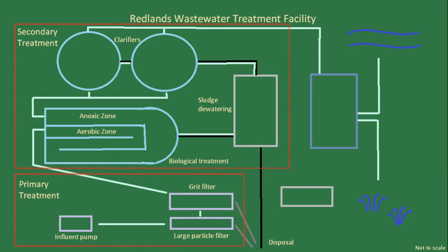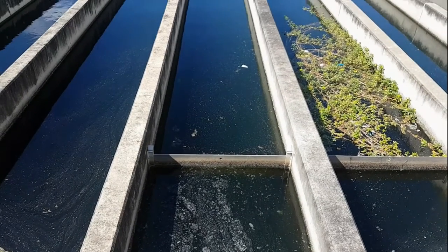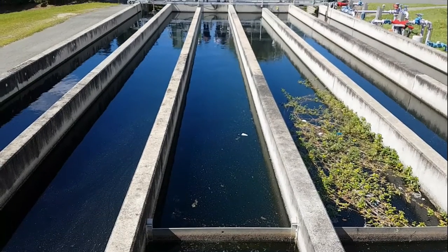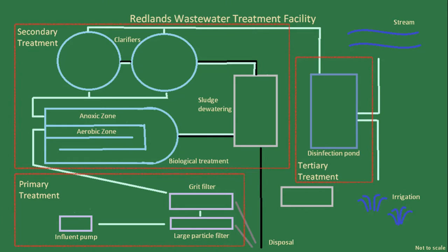Water released by the clarifier enters a small tertiary treatment phase. In this tank, chlorine is added to the water and kept in contact with it for just a handful of hours. In this time, the influent is sterilized, killing any latent microbes from biological processing. This would typically be the endpoint for a treatment plant that releases effluent into the ocean.